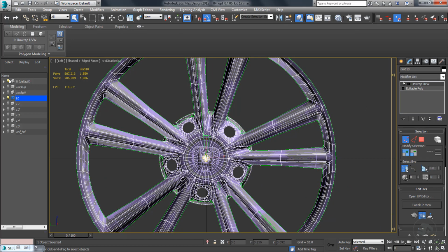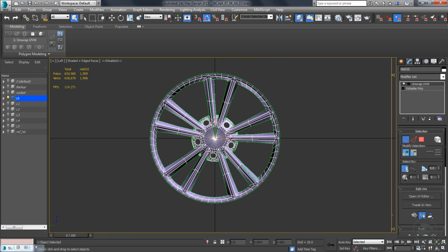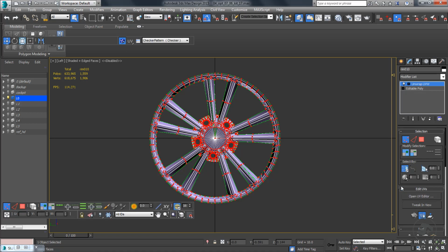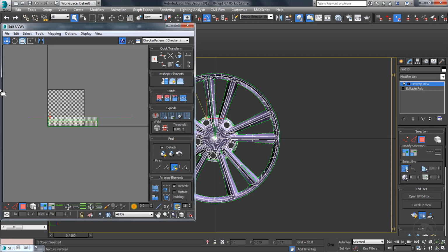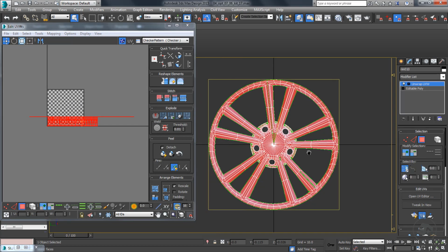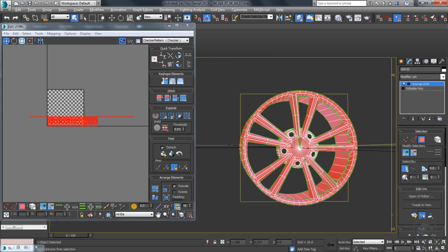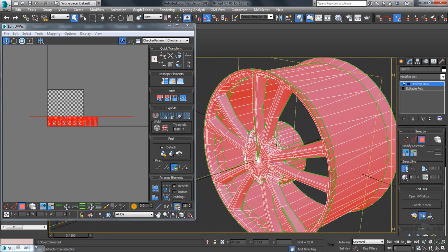The UV map we are going to create is just a template of UV coordinates to drive or guide the projection modifier. We shall need to adjust the final UV map for the L0 rim to make sure that all its geometry is placed on the right texture coordinates.